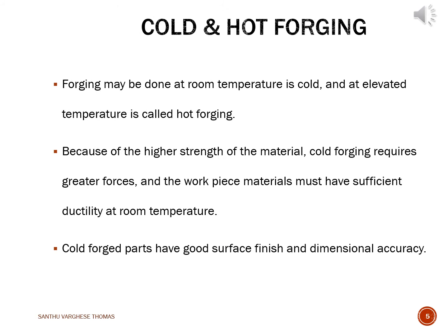In cold forging, as we told earlier, it is done at room temperature, and the hot forging is done at elevated temperature. Because of the higher strength of material, cold forging requires greater forces, and the workpiece materials must have sufficient ductility at room temperature. Cold forged parts have good surface finish and dimensional accuracies.